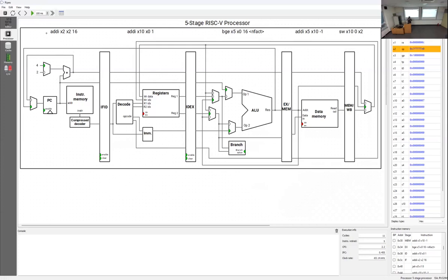The flush means that the instructions are cancelled. So the branch is in the ME state because in this architecture, the branch is determined by this branch unit. Then the branch is in ME stage, and we can fetch the correct instruction, the target of the branch. But these instructions need to be flushed, cancelled. You can find the flush here.